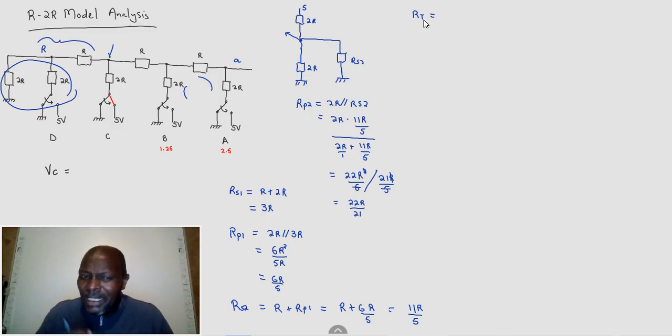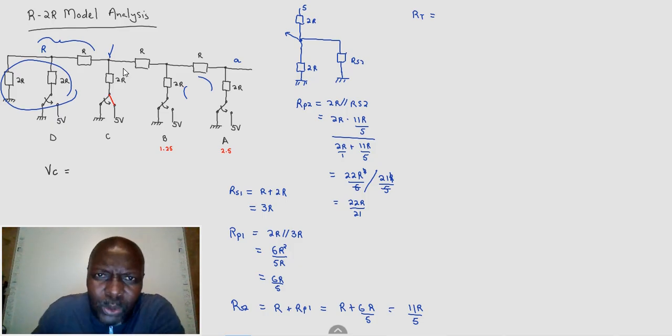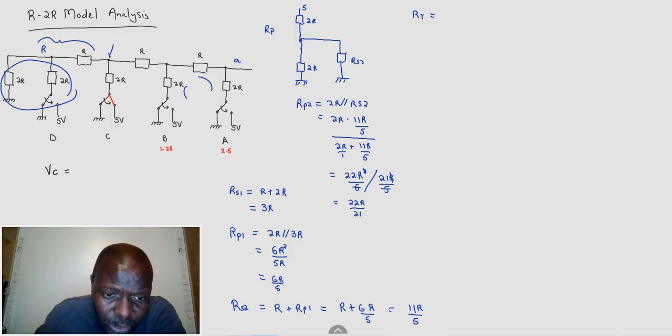All right. I believe that each instance has an easier way to look at it. What I'm doing might not, in your opinion, be the best way, but it works. Let's go on and say we want R total. So all you need to do now is add R parallel here at that junction. I should make it look at the junction there. R parallel is actually measuring these two parallel networks. This is what we call R parallel 2. So this R parallel 2 is looking there.